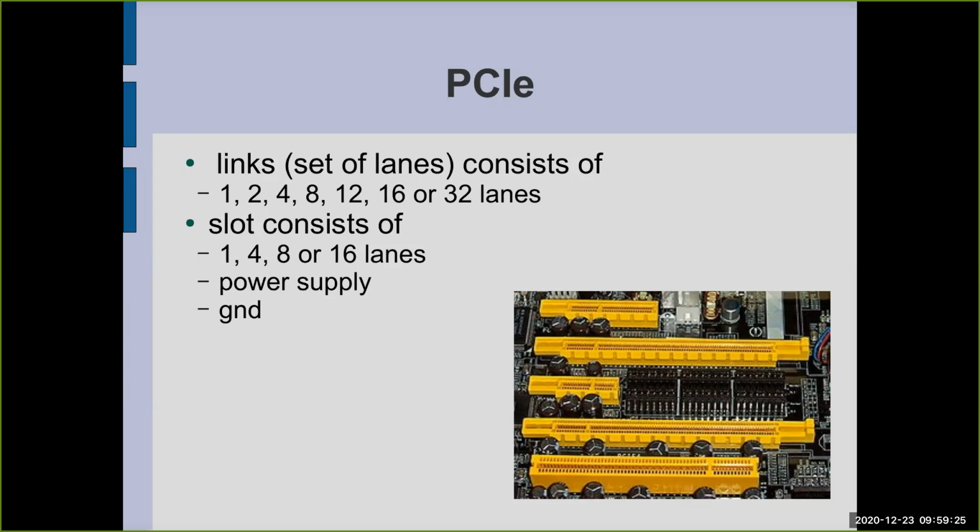So if your processor or chipset is able to handle, let's say, 16 lanes, and if you sum up all lanes or all slots you have on your main board, you can get a higher number of lanes from this calculation. So let's say here we have 16, so 32, 34, 38 lanes. Yeah, but your processor is able to handle only 16 of them.